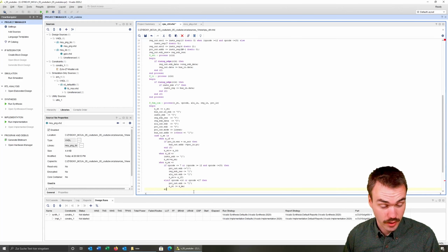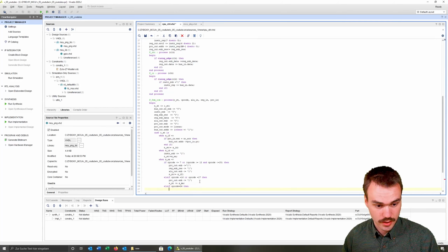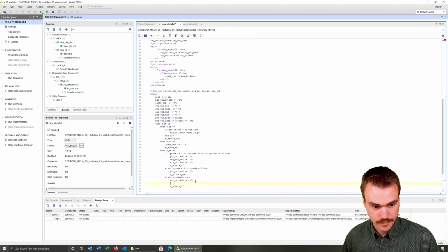And now we also have more complicated commands like a jump. So we could say the jump command is that address before. Then you can say again program counter enable is equal to 1, and the next state is state instruction fetch, and program counter out.mode is equal to absolute jump.